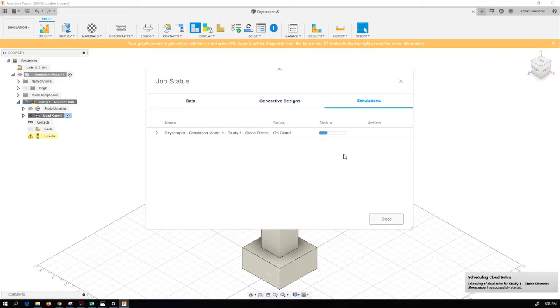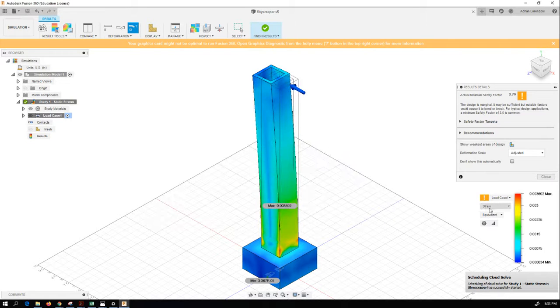Once again, this takes some time, but it's kind of cool what it gives us, so it's definitely worth waiting for. Okay, almost there. Close. We still got strain. Let's go to stress, and we're almost a third still, so we're just over 1,000. Once again, 2,900 is the max for yield. 4,293 is where it breaks. So we're still good.